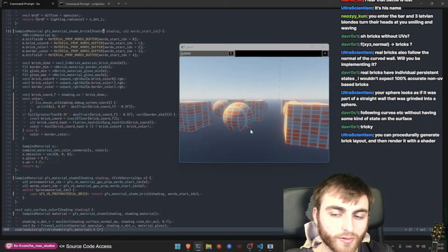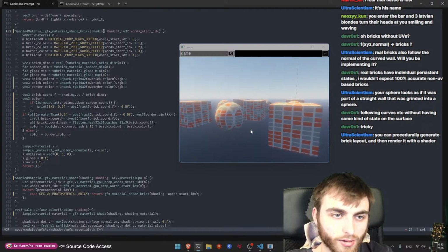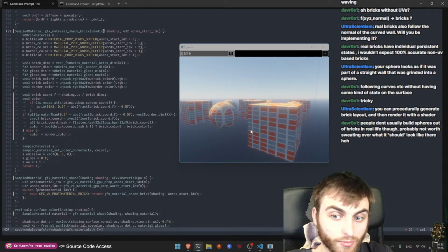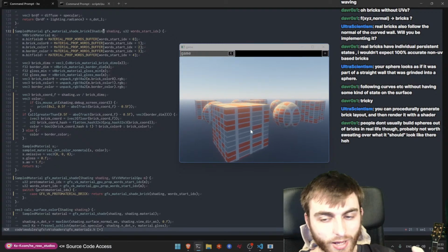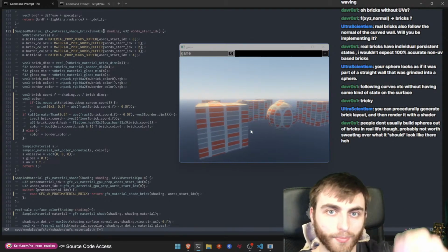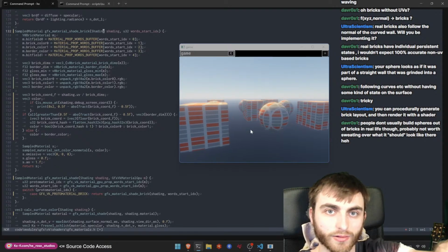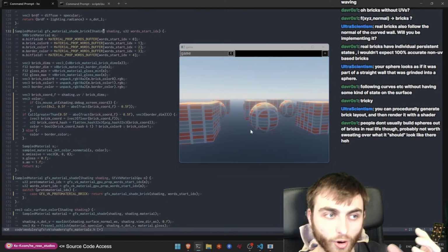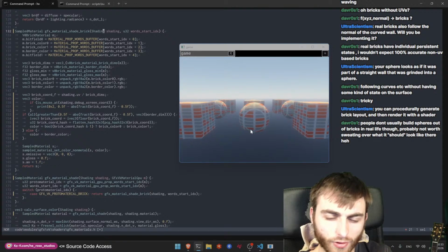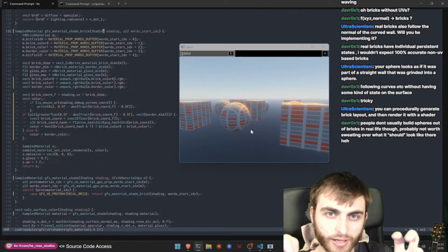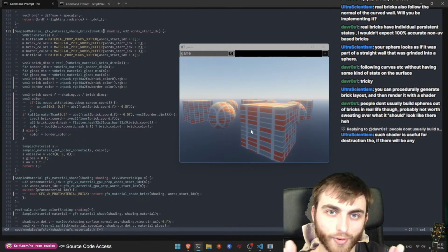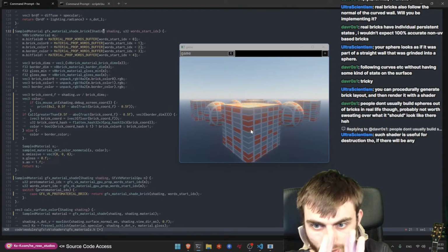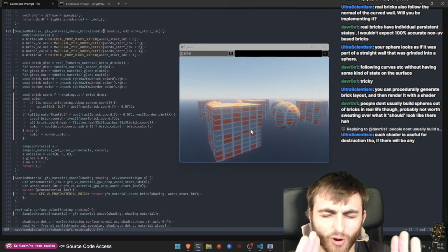These are the UVs that are applied. These UVs are taken directly from being in local space of the object. But when I have an editor, we will be able to paint down specific UVs, right? That's the thing. On the tessellated triangles of these objects, we can store different 3D texture coordinates and therefore get the wrapping rounds and stuff like this that follow the edges of the